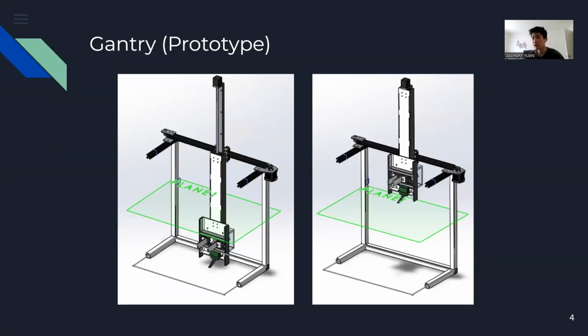Okay, moving on to the gantry subsystem. This week, we started integration with the actuator team for the prototype. As you can see, we've got some acrylic plates that we just mounted to our linear actuator mounting block. We try to mount it as close as possible to minimize the moment generated. And as it stands, it's under the loading capacity of the linear actuator, but we're still going to do some testing.